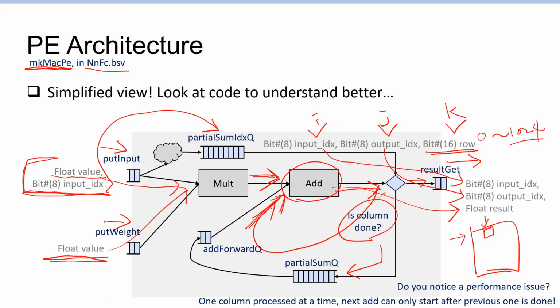But right now, the point is, even though the multiplier operator and the add operator are fully pipelined implementations, so even if they have multiple cycles of latency, you can always inject one request per cycle, that's actually not how it's being used. At cycle 0, let's say you push something into the adder. At cycle, let's say 6, the results come out. But over those 6 cycles, while the results come out and get pushed back in, no new requests can be pushed into the adder, which underutilizes the implementation, underutilizes the circuit.